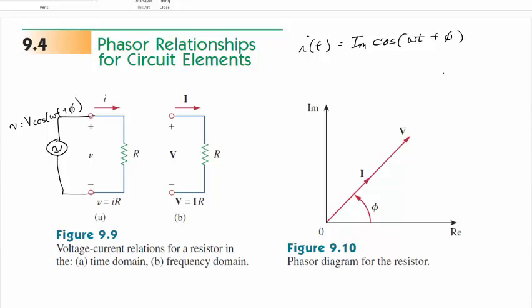So the phase really just means that at some particular instant in time, that I've called a zero reference point, my sine wave is not starting right here, but it's starting somewhere different based on some phase reference point that we've described. So that's all it really means. This is the most generic case of saying that I have a phase phi in here. But normally, when we talk about resistors, we'll put the resistor along the real axis. But anyhow, if I have a voltage and I have a current, they're in phase with each other.